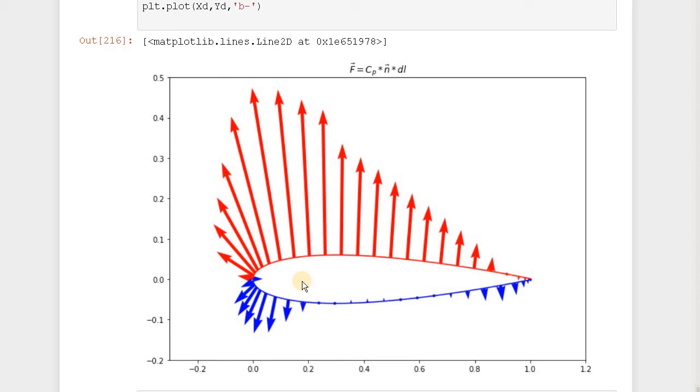But I completely forgot about the drag, because on each panel element you have the drag force acting. And you can get the drag force using some other command from XFoil, so you can extract the drag as well. So you have pressure and drag distribution. I think the drag is also available. So having the drag distribution and pressure distribution, you can compute the moment in the correct way. I just basically ignored the drag and got the results for the pressure distribution alone. So a mistake was made, and in my previous video I have incorrect graphs.